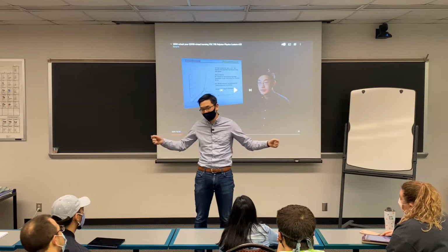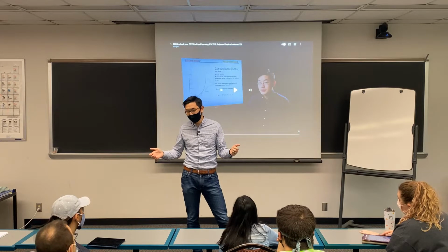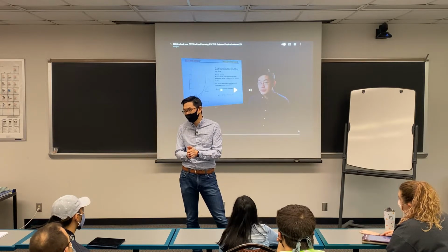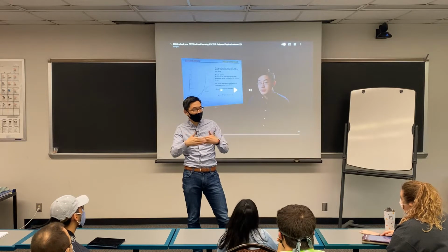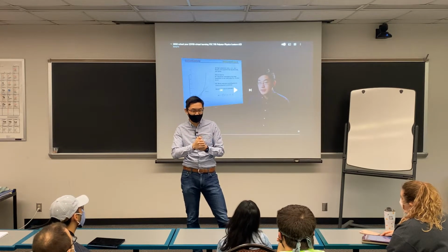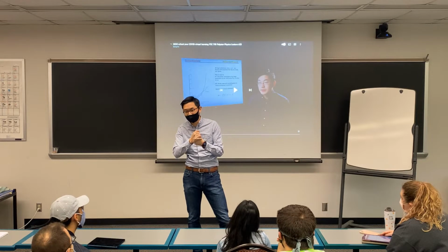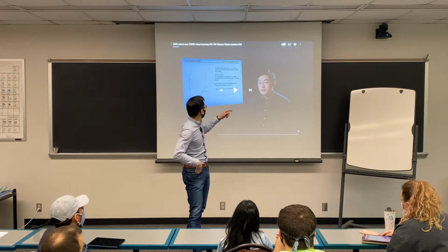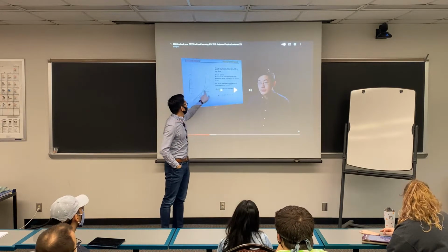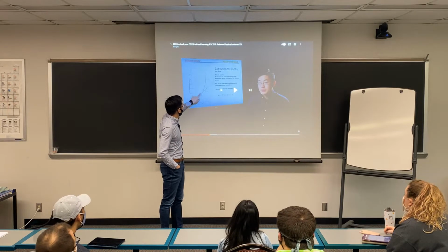However, once you draw it, you will create a special phenomenon called strain-induced crystallization. When you stretch it, its chains are aligned, and because of this alignment effect, you have a chance to make the polymer crystallize while you stretch it. Once you let it go, the crystallization just melts. So as you can see, when it's crystallized, it will have a strong deviation.